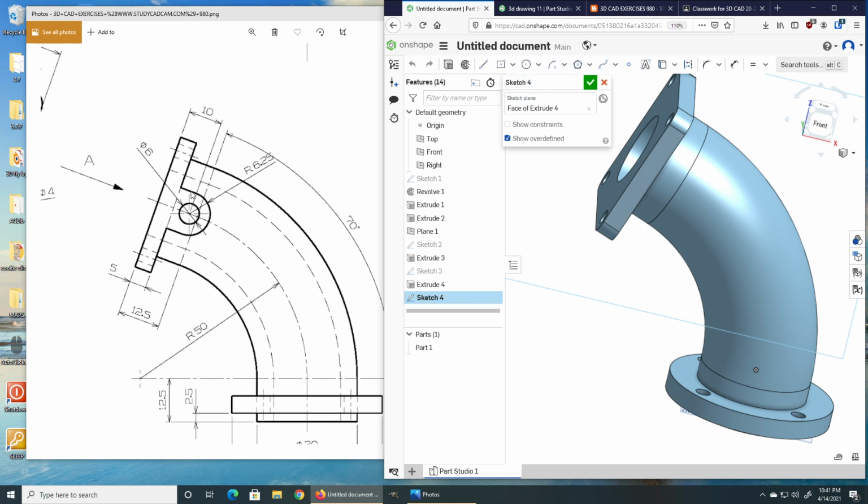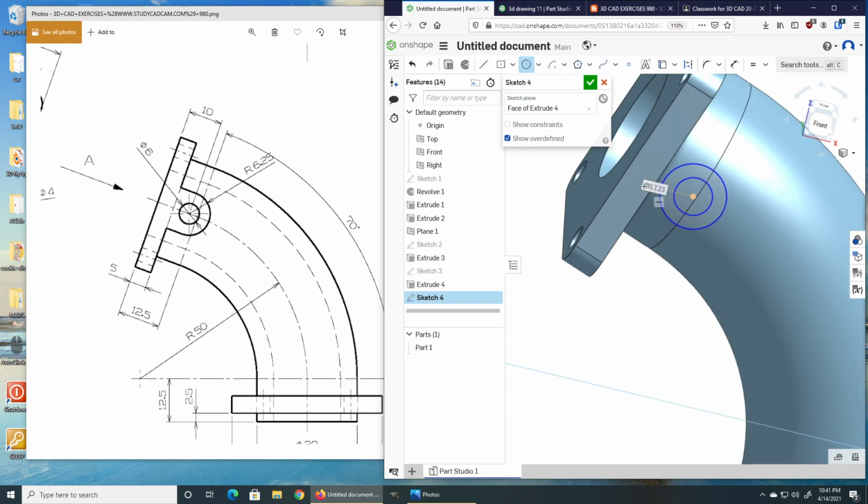This is basically 2 circles and some parallel lines. So I'm going to put a circle here and a circle here. Look how careful I was about those placements. Not at all. I am going to dimension the little one, diameter of 6. The big one has a radius of 6.25, so we're looking at 12.5.